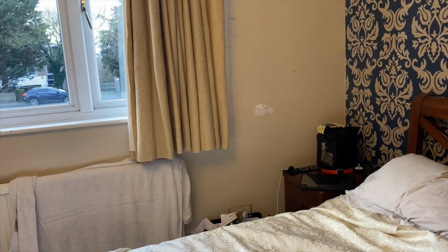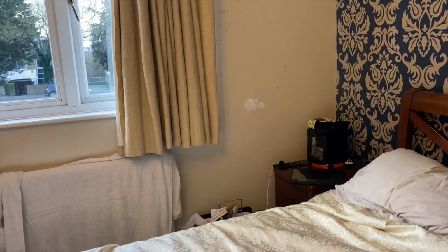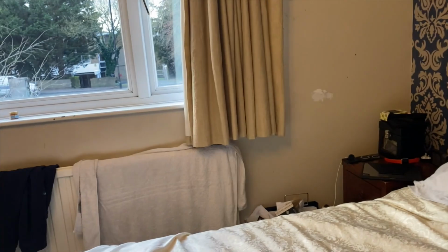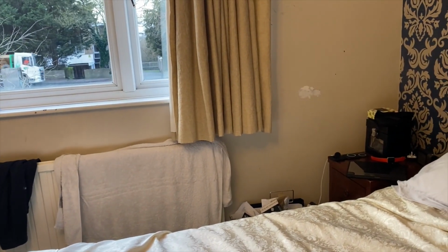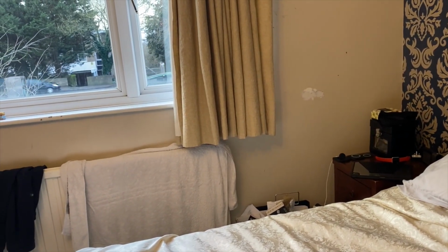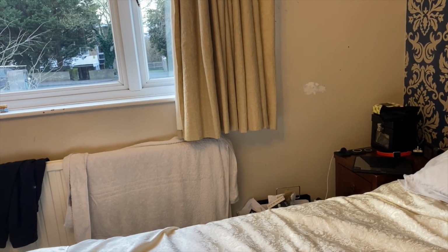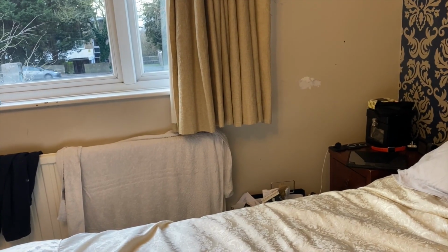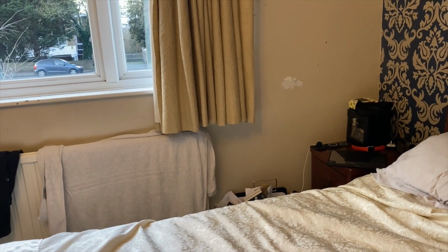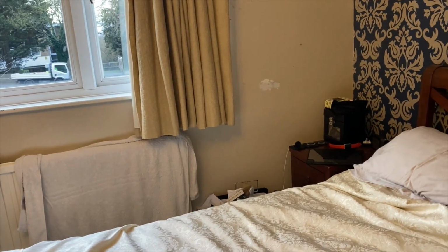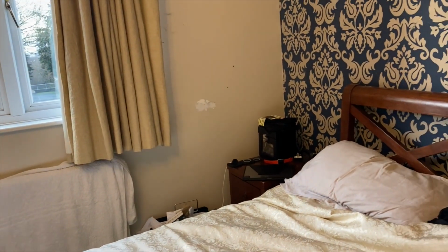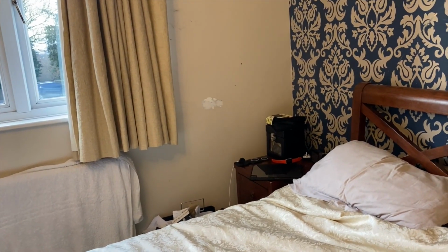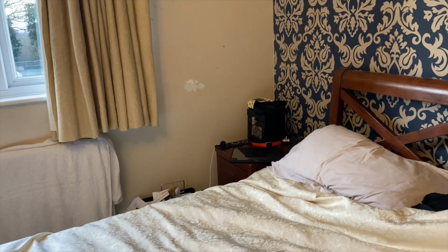So this is on the south side, is it? Is this where the sun's coming? So the sun that's east. So that's south. Yes. So that means that you're going to get much more sun, and it's going to get warmer during the day and colder at night. So you get more expansion and contraction. Right, okay. So that explains a lot. It explains the cracking, but it doesn't particularly explain why you're getting the mold. Typically you're going to get mold more on the north side than the south side.